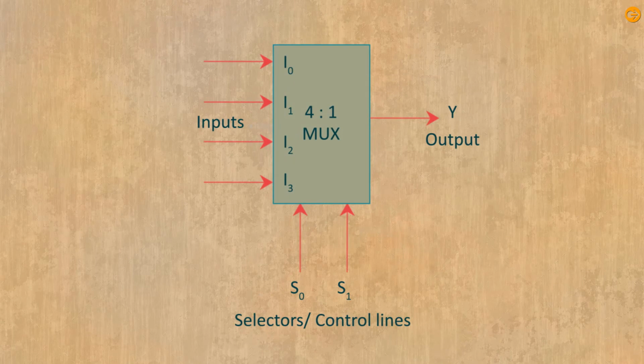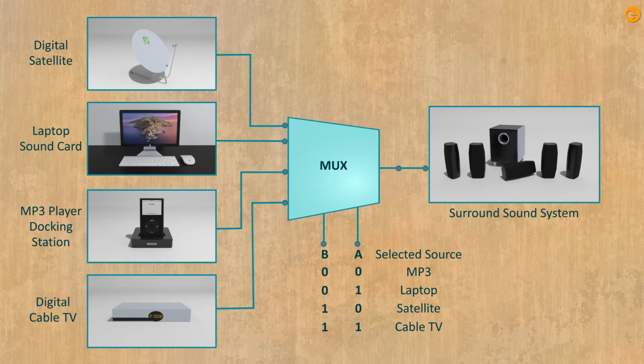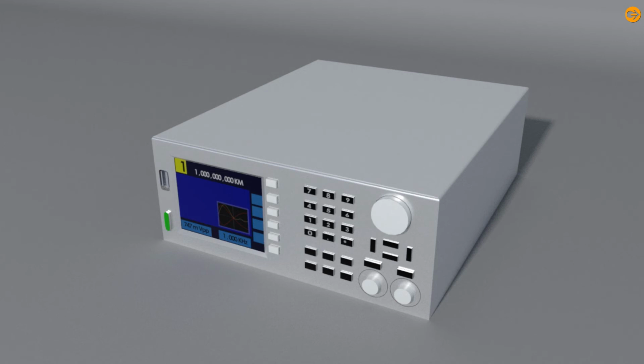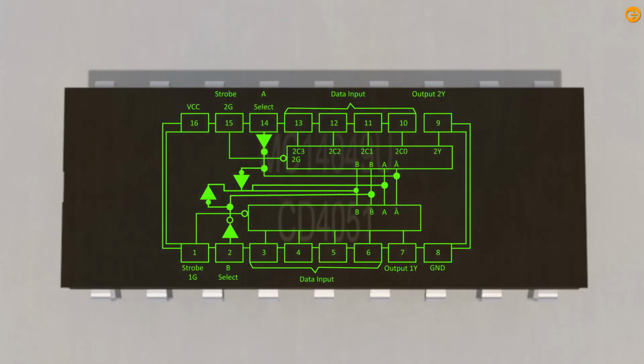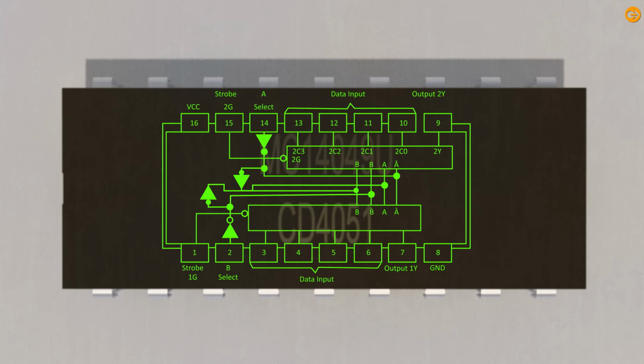In digital system applications, multiplexers find immense usage since this allows several inputs to be connected independently to a single output. These are found in a variety of applications including data routing, logic function generators, parallel to serial converters, and so on. The DIP image of IC74153 is shown in the figure. This is an integrated chip of a multiplexer.